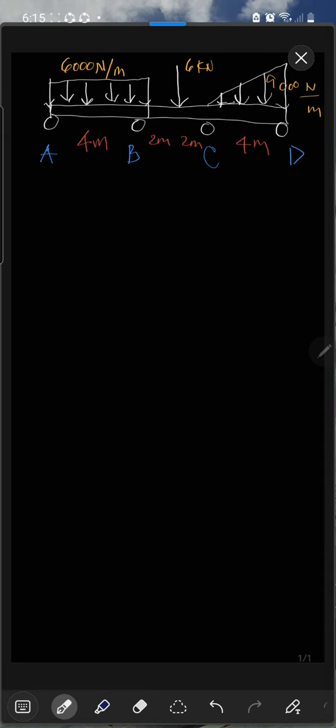Okay, so this one is a hinge. When the far end is a hinge, it is considered that your relative stiffness is only 3/4 as stiff as the fixed. So you multiply 3/4 to the relative stiffness.